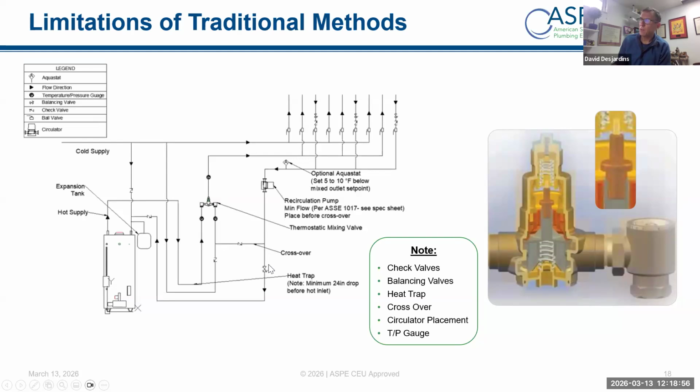If that doesn't get done, the hot water is going to get pushed through this hot side, and the seats on these valves don't have positive shutoff, so you're going to have temperature creep overnight with low usage. You'll notice the check valves, where hot and cold would otherwise collide. We want to keep those separate, so that's their job. Then there are temperature and pressure gauges, so we can look at what's happening in and around the valve. That's important, and it's just common, good practice.